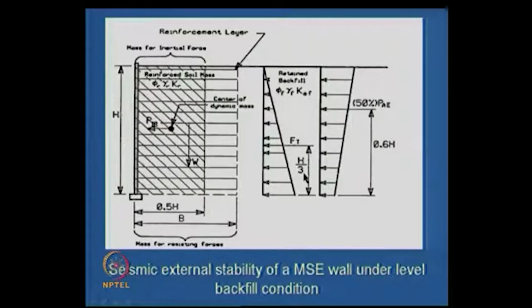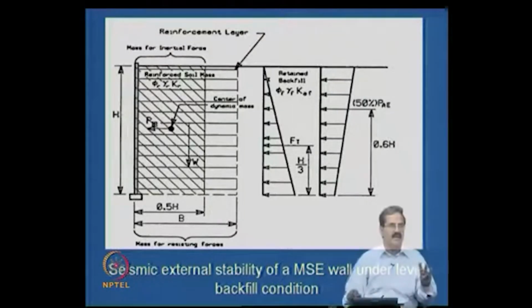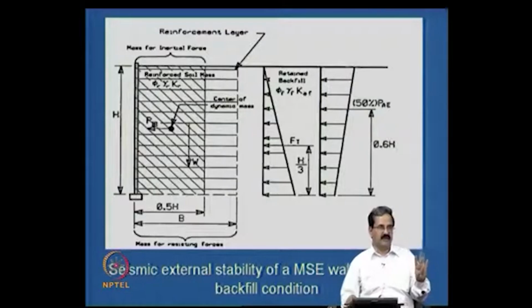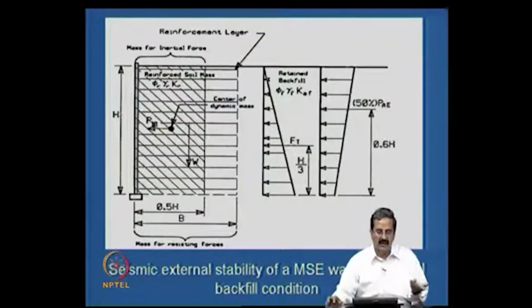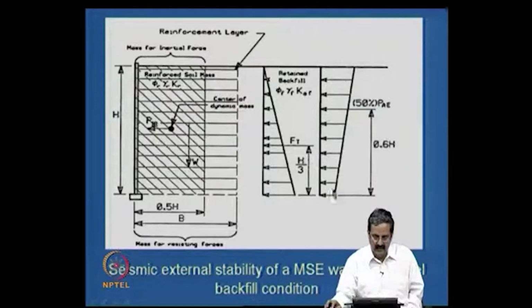These are the things you have to calculate: sliding forces, the factor of safety with respect to sliding and overturning, and even the bearing capacity check and all that. This is very important when you are trying to assess the stability of the reinforced soil under earthquake conditions. Of course, the codes give much more detailed matter, and you have software as well, but one should be very careful in understanding these provisions properly and then applying these rules.